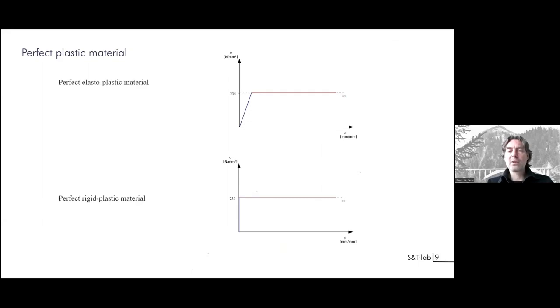What about the context of applying this theorem of plastic design? You are normally supposed to use a perfectly plastic material. It means that as soon as you leave the elastic zone, you are in a zone in which you have plastic deformation, and the force is maintained in the structure, whatever the deformation.